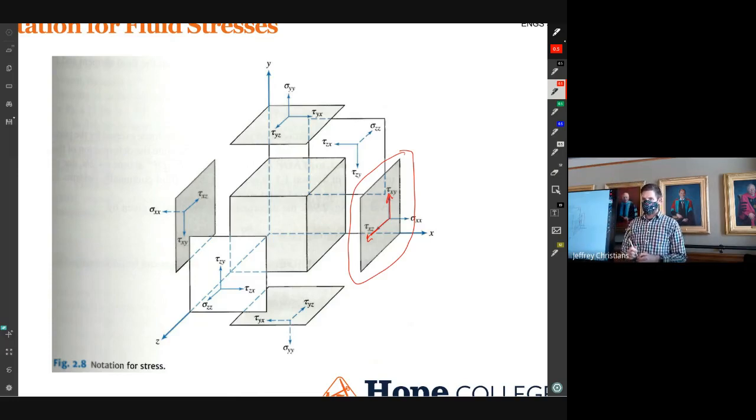They're a little bit different because solids are elastic and fluids are not. If you have a shear in a solid, maybe you would talk about at what point you actually get buckling in that solid, or if you have a normal, what's the deformation? In a liquid, we don't have just elastic deformation, we have movement. So the challenge for fluids is to figure out what type of movement these different stresses result in, and how can we talk about that?